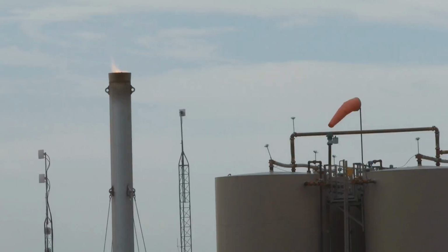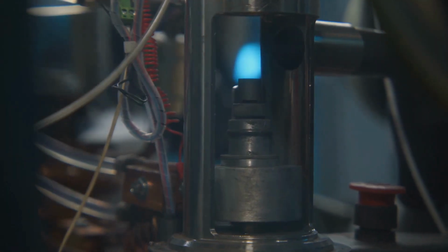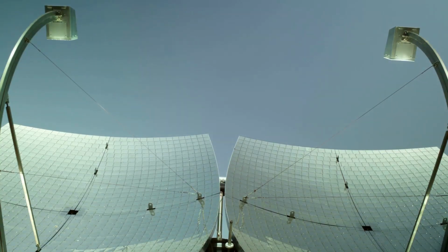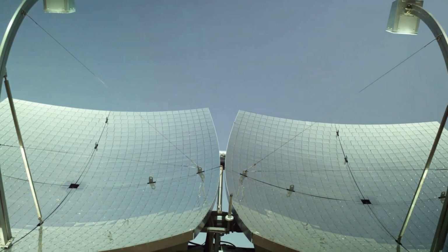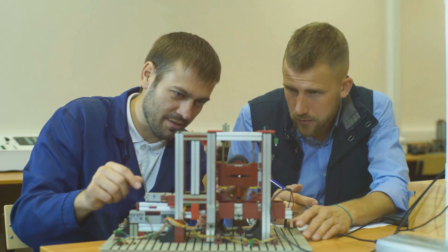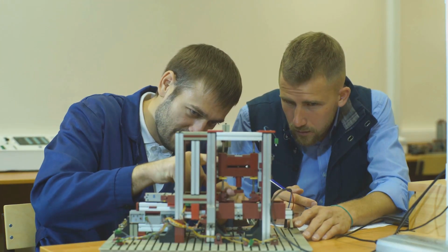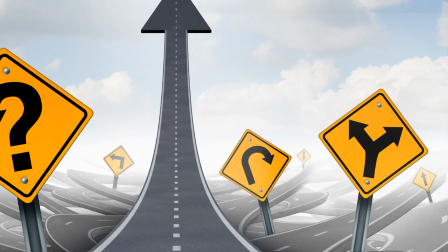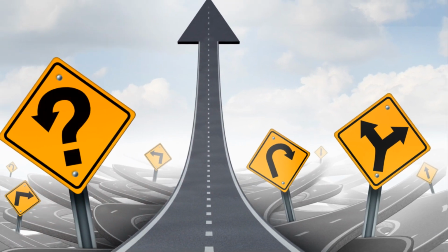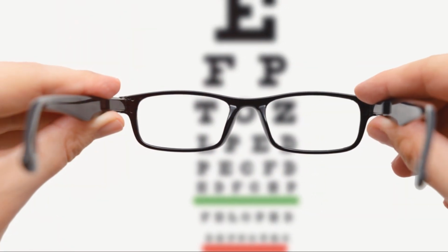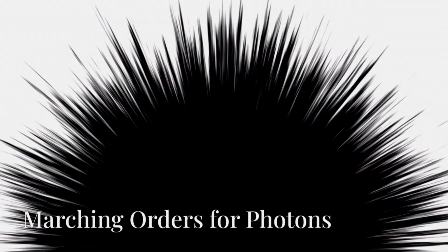However, S2S has limitations. It stumbles when dealing with participating media, like combustion gases or pulverized coal flames. These media absorb, emit, and scatter radiation, making the path of photons less straightforward. In such cases, other models like DO or DTRM are more suitable. Despite its limitations, S2S remains a valuable tool for many engineering applications. Its simplicity and speed make it a popular choice for design optimization and preliminary analysis. It's essential to understand when its assumptions hold true to ensure accurate results.